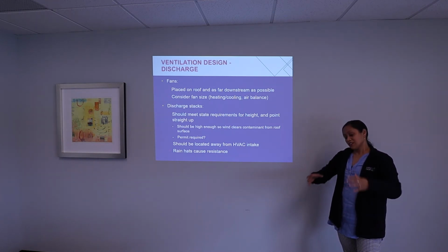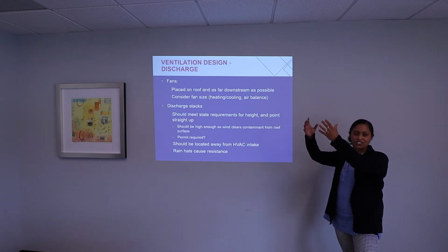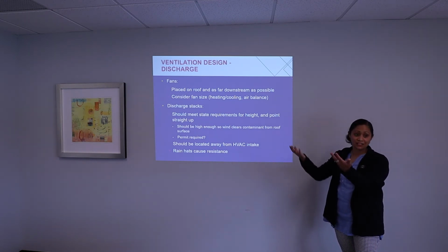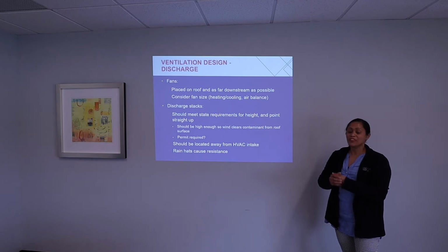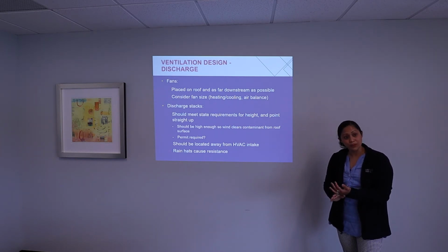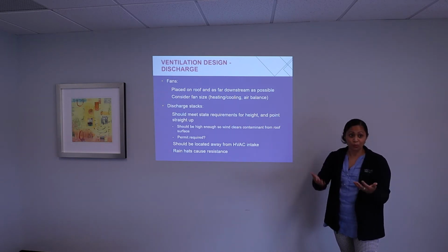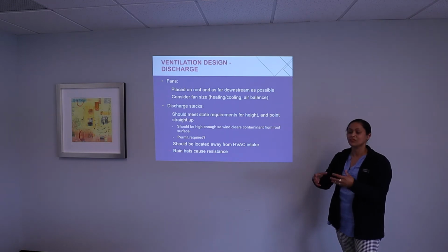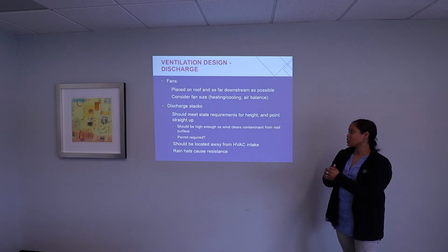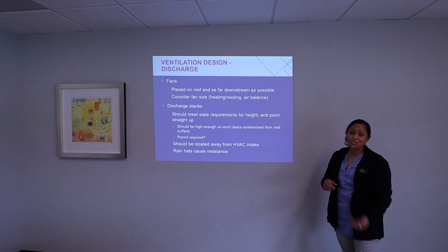On top of that, there are these discharge stacks where the contaminants now leave the building. And they do have to meet state requirements. So every state has different, I would say, air permitting requirements as to things like the height and other factors. And yes, they should point straight up.